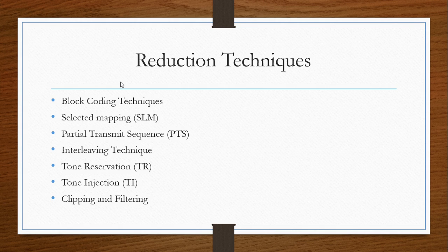The main idea behind this method is to increase the constellation size such that each point in the original basic constellation can be mapped into several equivalent points in the extended constellation. Since all information elements can be mapped into several equivalent constellation points, these additional degrees of freedom can be utilized for PAPR reduction. The drawbacks of this method, however, are that it needs side information for decoding the signal at the receiver side and causes an extra IFFT, the inverse fast Fourier transform operation, which makes this technique more complex.